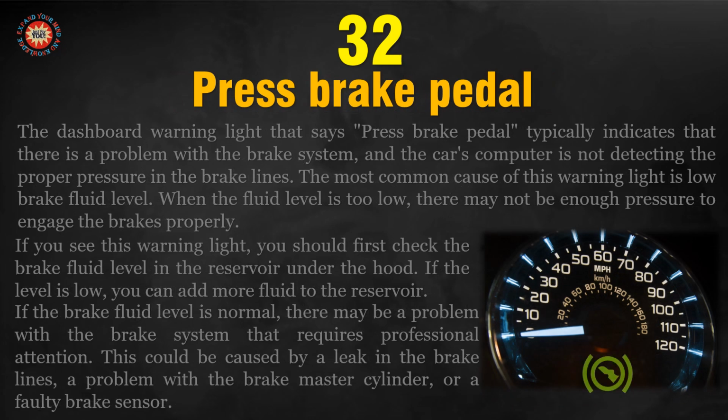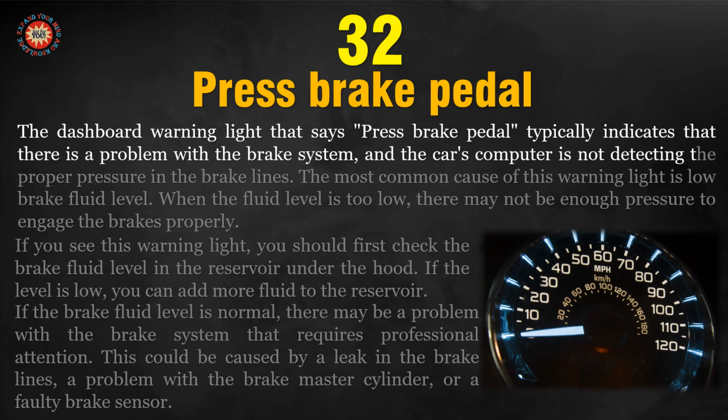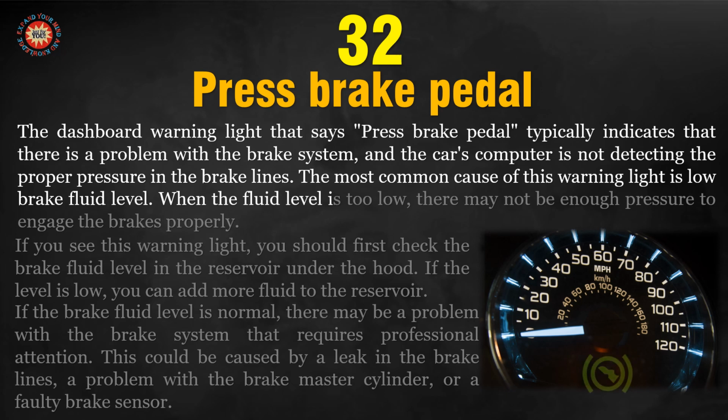Symbol 32. Press brake pedal. The dashboard warning light that says press brake pedal typically indicates that there is a problem with the brake system, and the car's computer is not detecting the proper pressure in the brake lines. The most common cause of this warning light is low brake fluid level. When the fluid level is too low, there may not be enough pressure to engage the brakes properly.